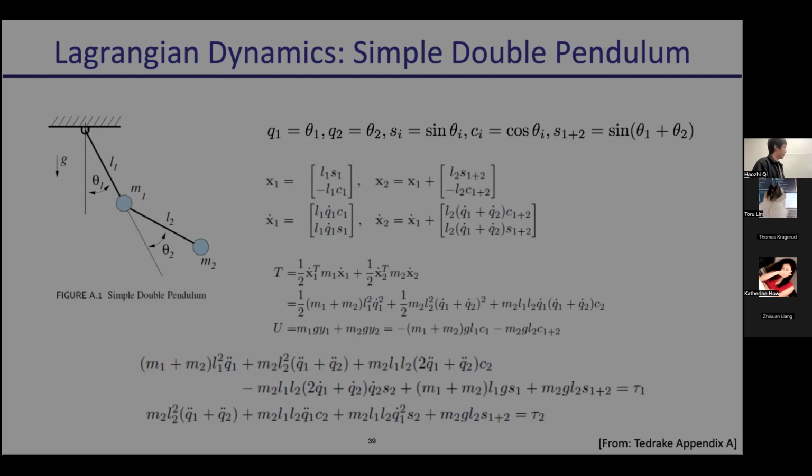And it's kind of easy to get a relationship between the Q double dot and the torque you applied on the joint. So remember our purpose is to get accelerations of different joints, according to your external control input. So in this case, all the other quantities are known, and we can get a relationship between accelerations and the control input. So this is how at each time step you update your angular velocities, and then as a turn change your velocities and also your positions.